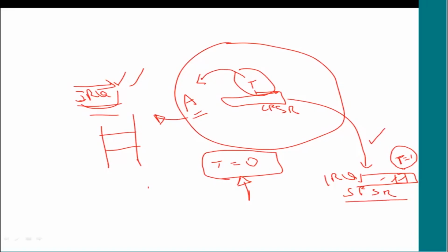Now when it comes back from the exception into the original instruction, it could be a thumb instruction or an ARM instruction. Assume both are in user mode. If it happens to be a user mode thumb instruction, it will come to know whether it is coming back to thumb mode or ARM mode as soon as it copies the SPSR into CPSR.